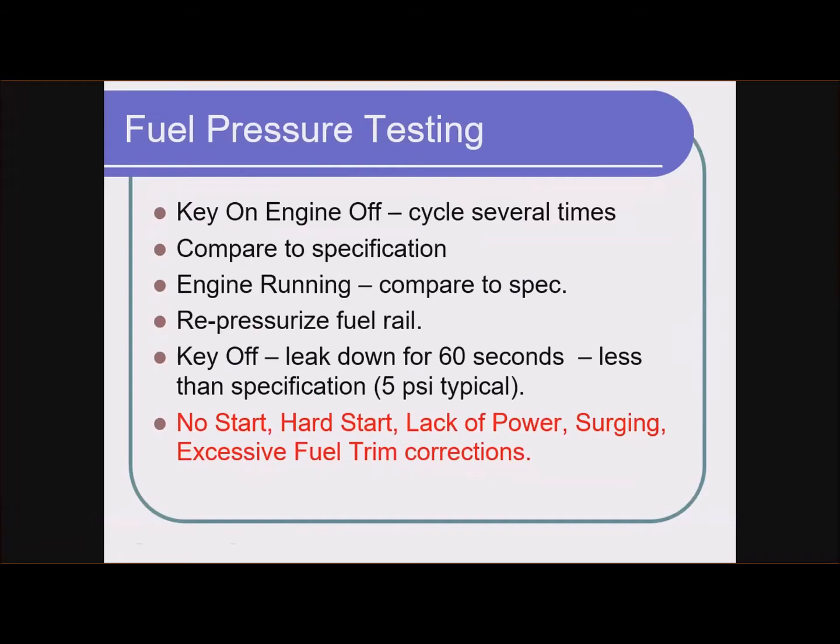And then as you accelerate and the engine vacuum drops, so if you stomp on the accelerator, you know that engine vacuum can go almost away. It can almost go to atmospheric. The vacuum goes away from the pressure regulator, allows the spring to push harder and causes the fuel pressure regulator to hold a higher level of fuel pressure.